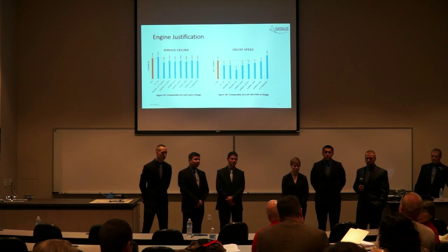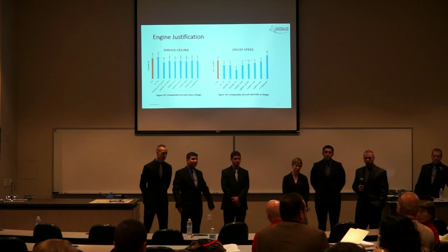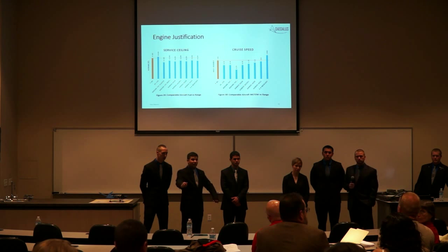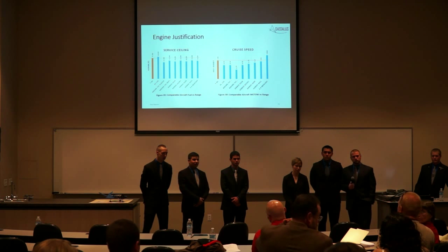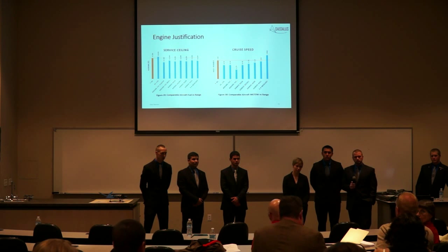Hold that for a moment. The question came up about where your boundary layer suction comes from, and it comes from the bypass. Now, what do you do in the case of an engine stall, whether it's temporary due to a gust or an actual engine stall, and now you don't have that suction source to reattach or shrink your boundary layer?